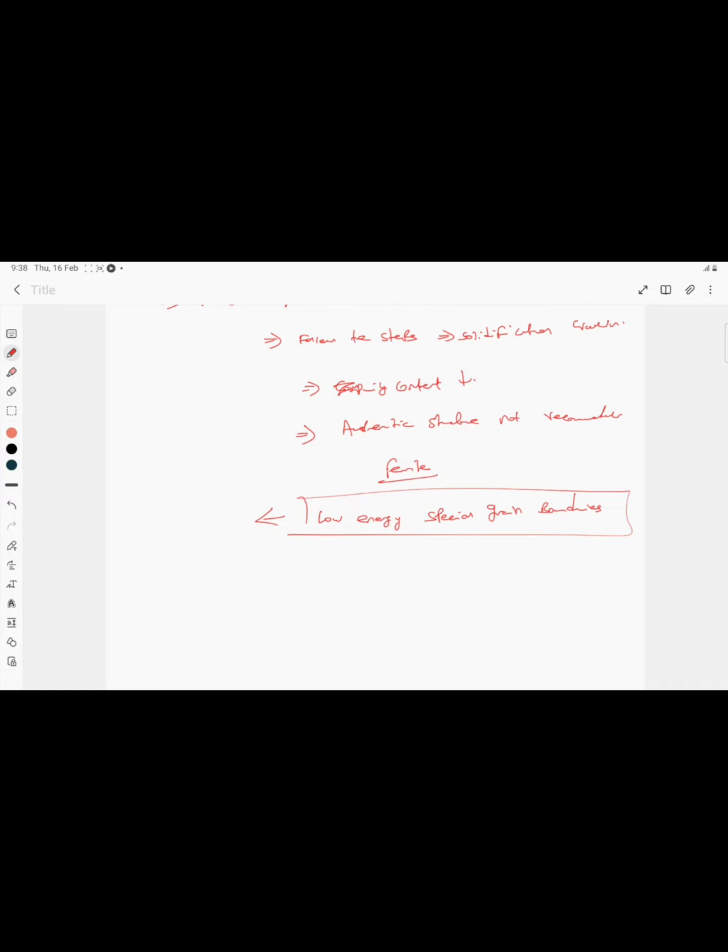And we have to minimize the amount of titanium and niobium in the material, but it is not possible in all cases, since they are intentionally added to promote certain properties in that particular material. So these are some of the steps that we can take, along with the other steps which we have discussed in solidification crack prevention.